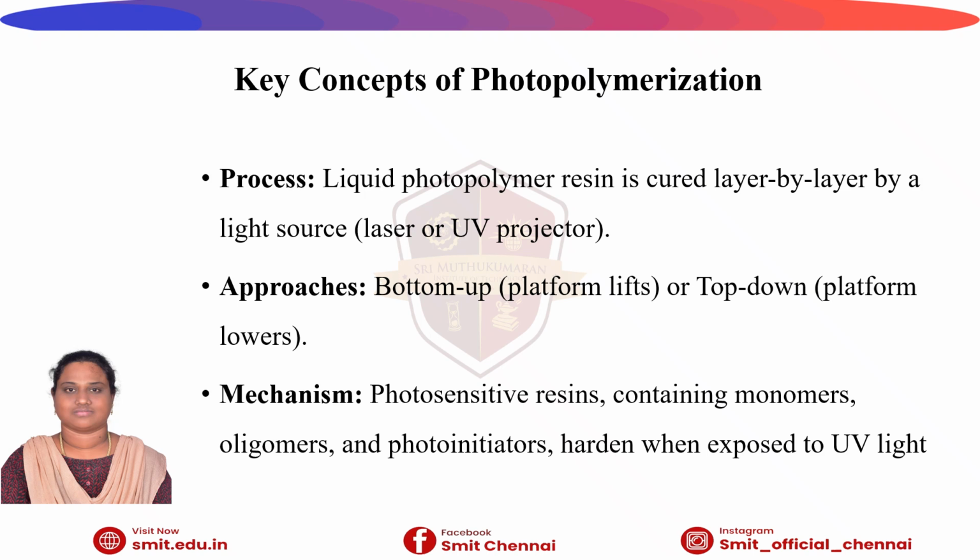Next, approaches. There is the bottom-up approach. The build platform starts near the transparent bottom of the resin vat and lifts upward after each layer is cured. This approach uses less resin and is common in desktop SLA and DLP printers.